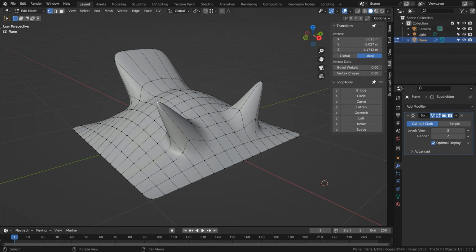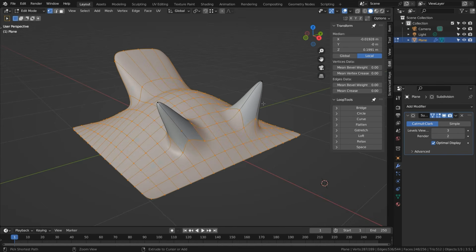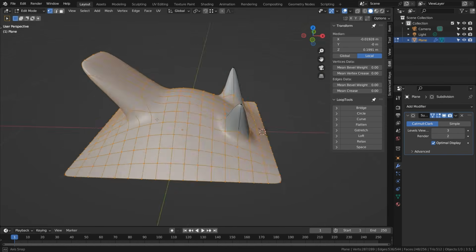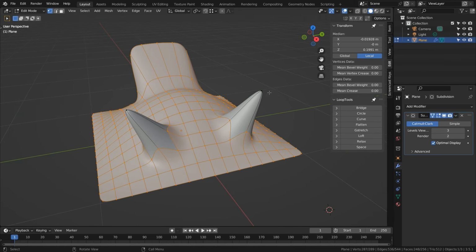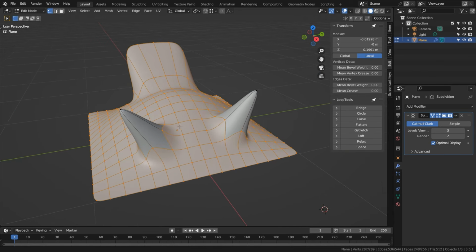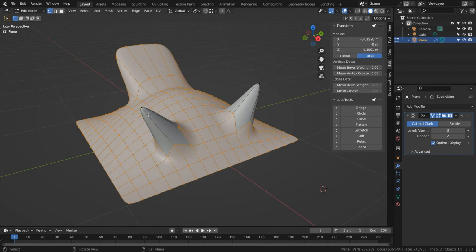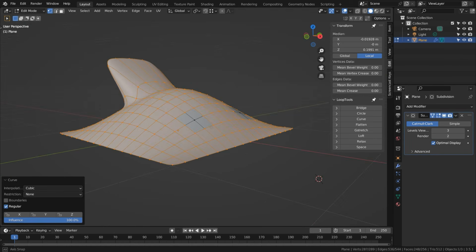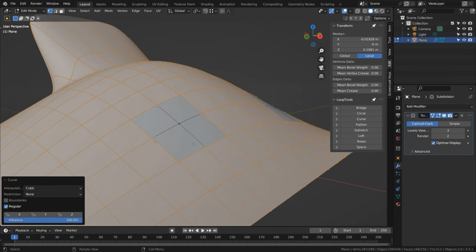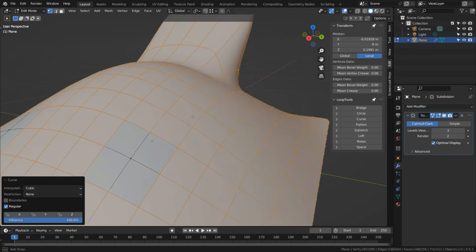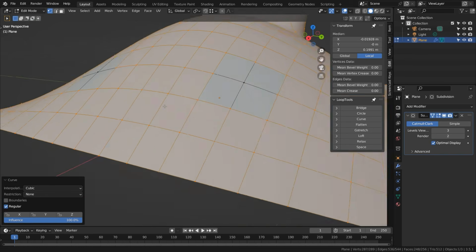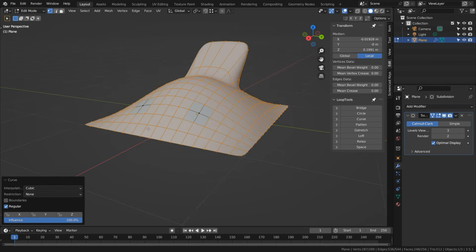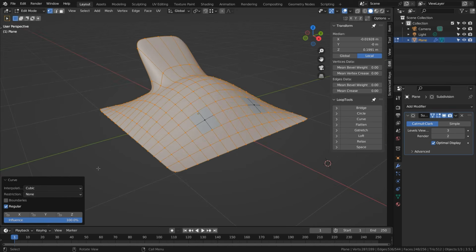What we do is we select the points we don't like, then we press Ctrl and I to invert the selection so that the rest of the mesh is selected and our problem points are unselected. And remember that I said the curve tool only works on unselected vertices. So if we press the curve tool at this point, then Blender will rebuild the curvature using these unselected points, but with respect to all of the curvature surrounding it. And that's all calculated cubically, which effectively makes the continuity perfect. And that is really impossible to do any other way.